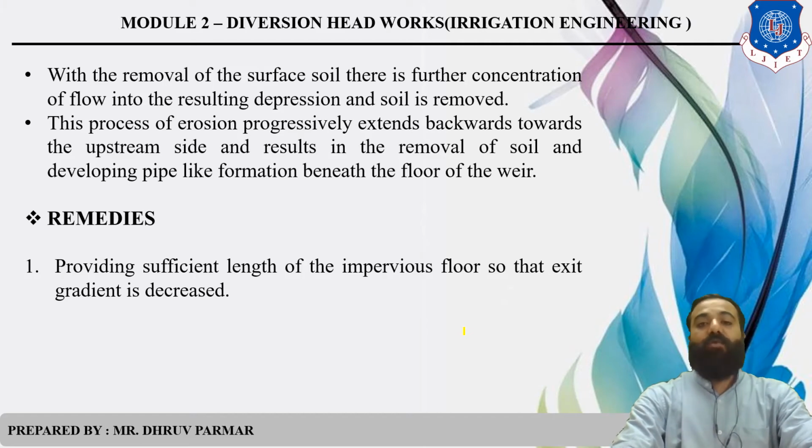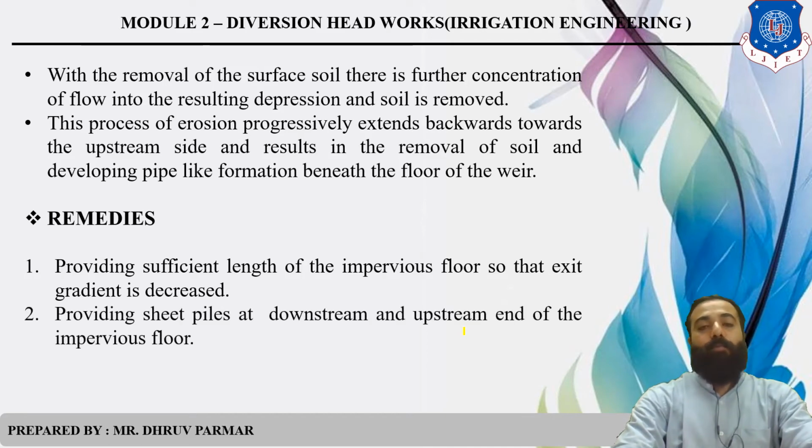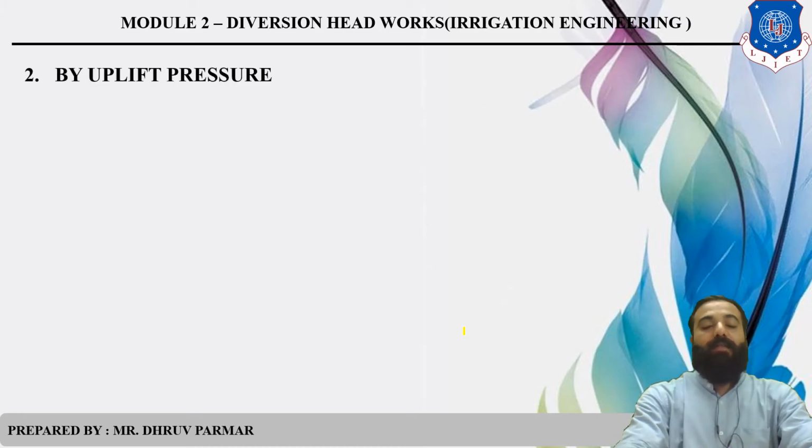First, you can provide an impervious floor so that the exit gradient will be decreased. Second, provide piles at the downstream side as well as the upstream end of the impervious floor.